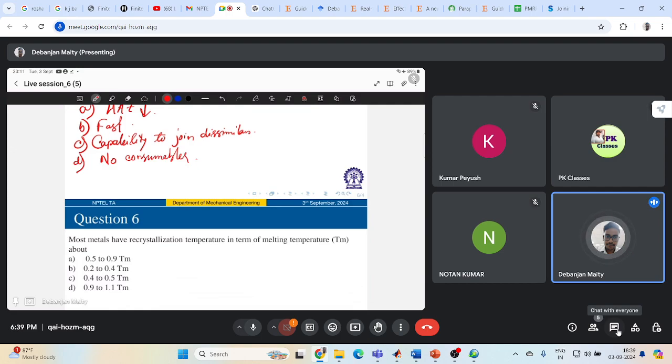Over here, your workpiece will be positioned near some magnetic coil or actuator through which you can generate pulses. I was talking about this capacitor bank, which will be discharging a high current pulse into your coil and it will create that magnetic field, right? And the opposing magnetic field will create a repulsive force that will drive one of the workpieces at high speed towards the other.